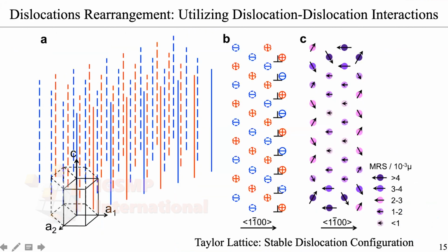And if we think a little bit more, not only focusing on the grain boundaries, because we can have these regular patterns of the dislocations, and then we can induce the next array of the dislocations, with these so-called positive and negative signs. Then there are interactions where the stress fields become more like the energies will become minimized, and then the force applied to each dislocation can be less than the force needed to induce the movement of that, and in that way we can have these stable dislocation configurations.